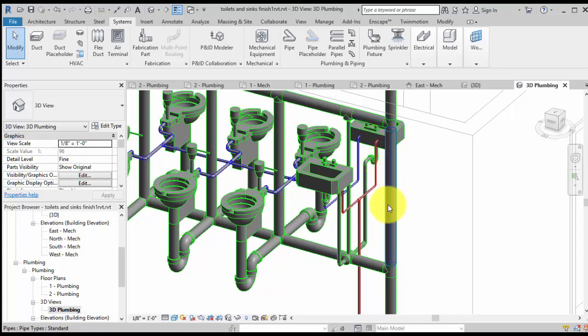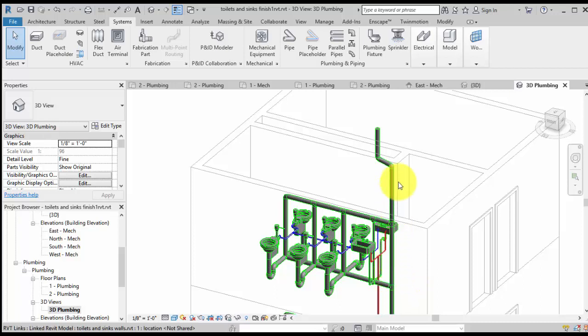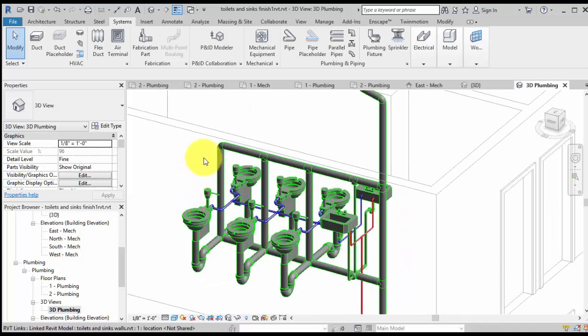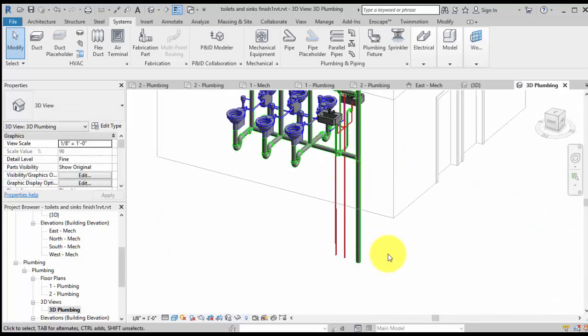So there is a water distribution system. There is also a drainage system called the sanitary system that carries the gray water away from your building. And then this goes all the way up as a vent stack for creating some vent so your water can be drained properly through your building. The rest of them have a connection, so the air can help the flow of the water, the gray water, carrying that away from your building and all the way down to the city sewage. We don't want to go any further on that.